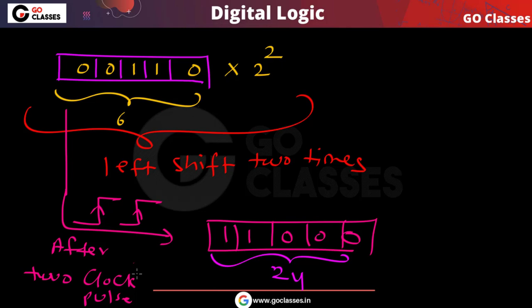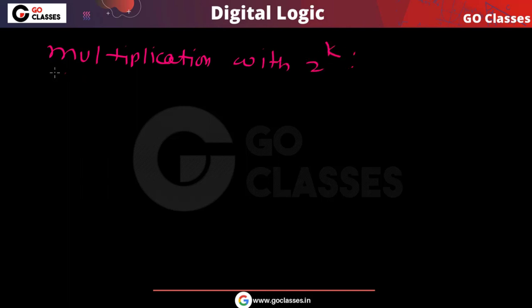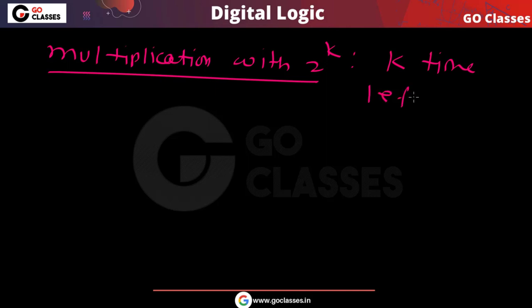So you can notice if you want to multiply with 2 power k, that simply means k times left shift. So I can say k times left shift. You can notice this is the left shift register. This is the application of the left shift register.